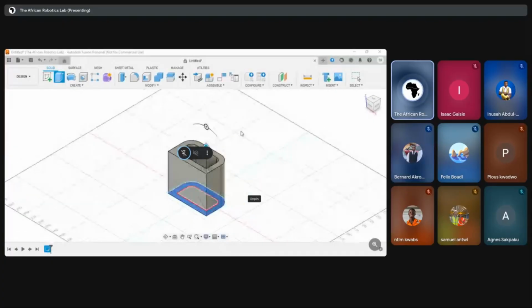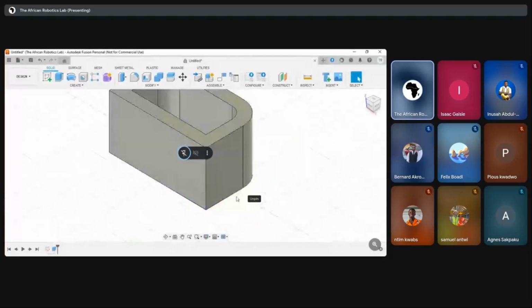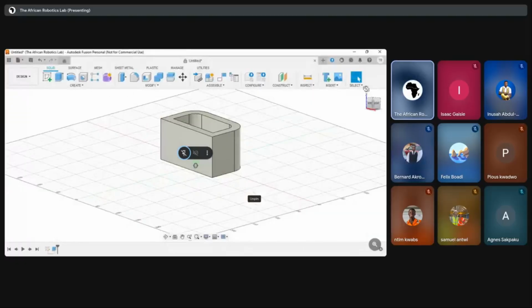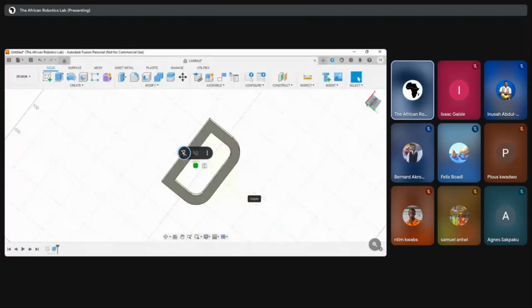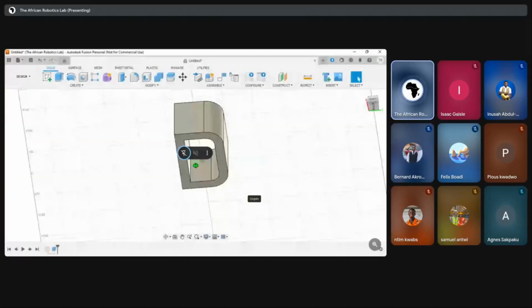After that, we extruded it to 120 millimeters, and that's fine. Or let's say we want to extrude it by 70 millimeters. We just have to type in 70 millimeters, then click enter. Right after we click enter, we now have our 3D body here. We can use this particular tool here to see how it looks, and this is how it looks. I believe this was very simple.